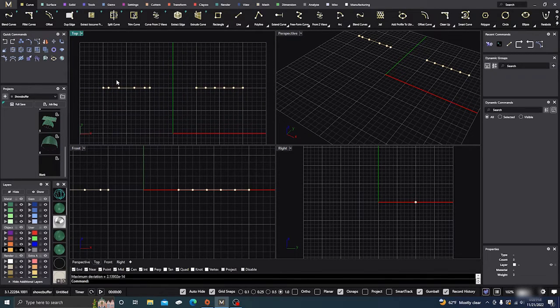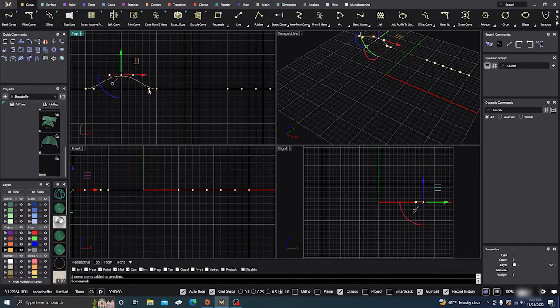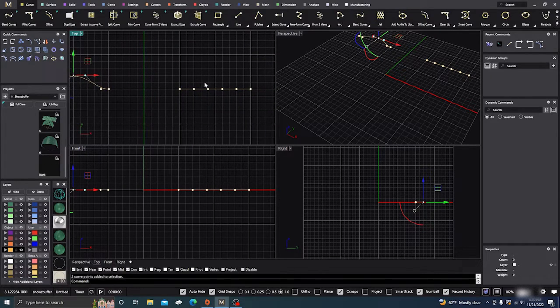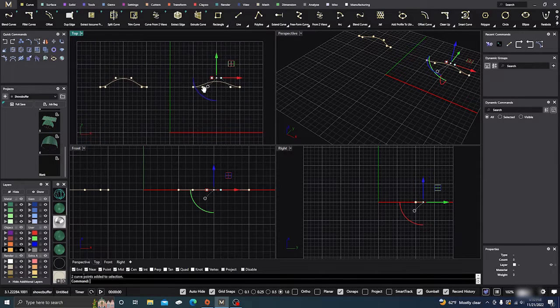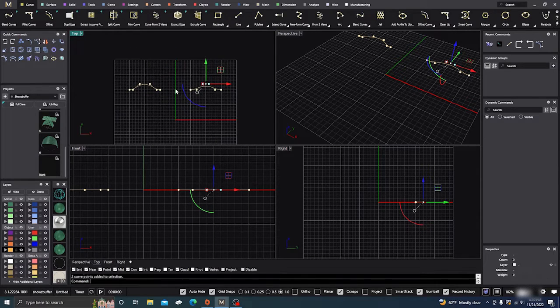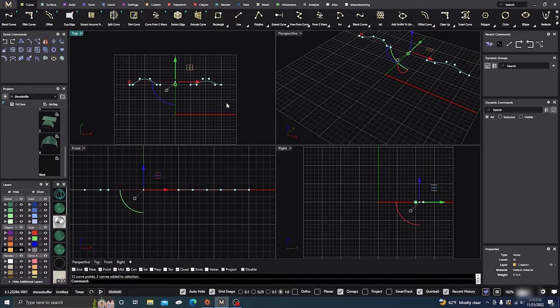Again, if we take these points here and jack them up 2 millimeters, it gives us pretty close to the same surface, except we have points dragging it down here, and you can actually change the weight of points, which maybe we'll cover in another video. If I take these 2 points and drag them up, we get a little bit smoother surface, right? It's not so sharp. So keep that in mind as we move forward.